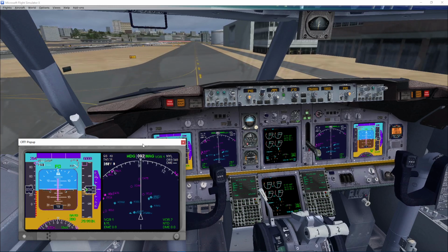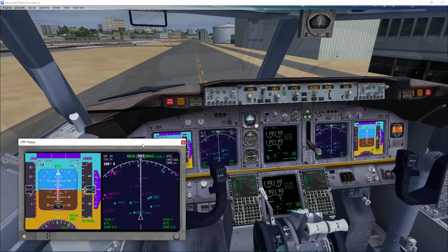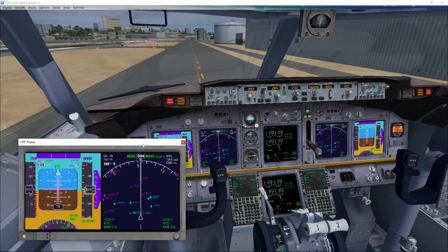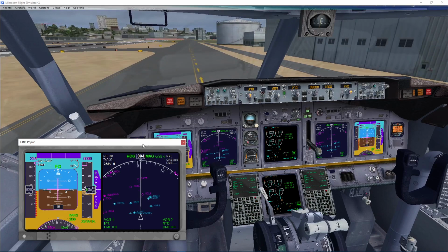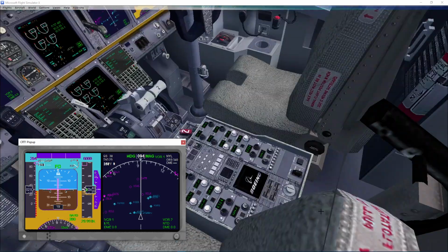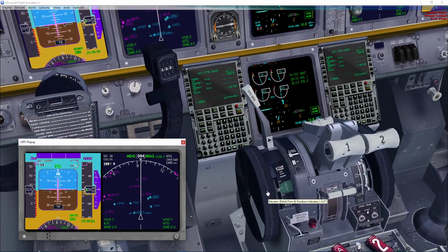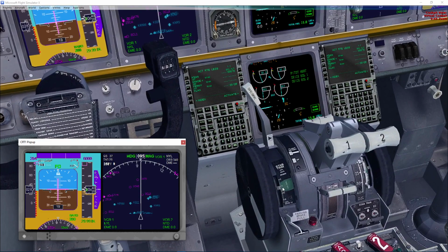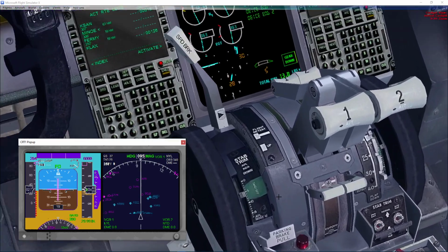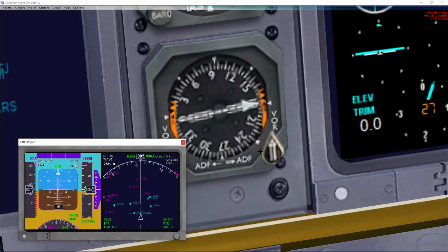As you can see, I don't calculate all of the altitude and the flap settings and the weight, and one other thing I usually do, I forgot here, is I set this trim up, but I can't now, and I usually set it up just a little bit more. It should be in the center of that green, so I'd move it up just a little.